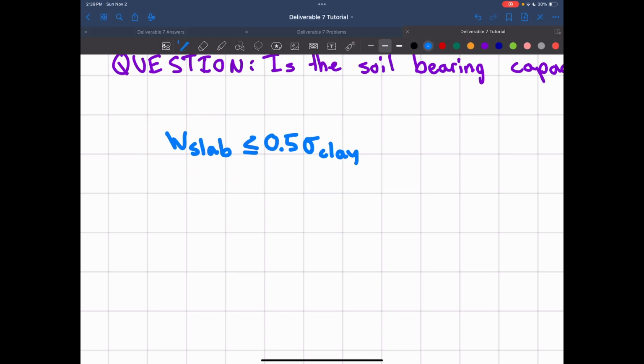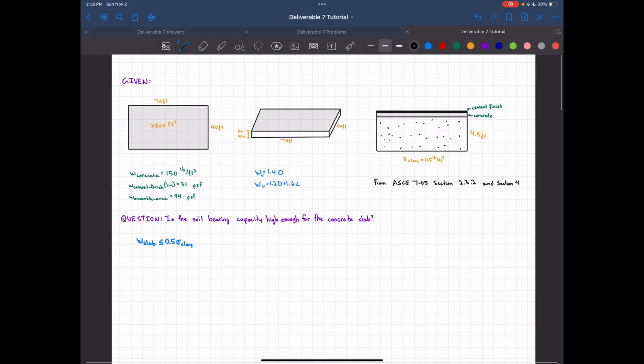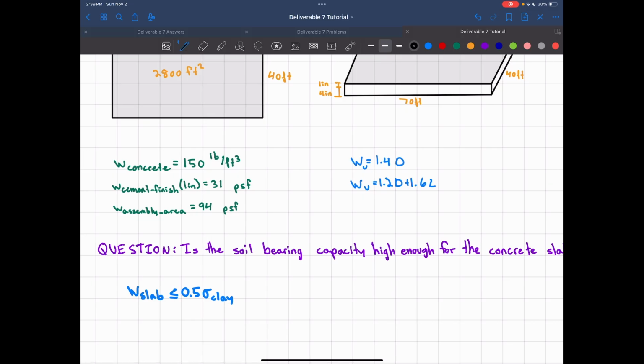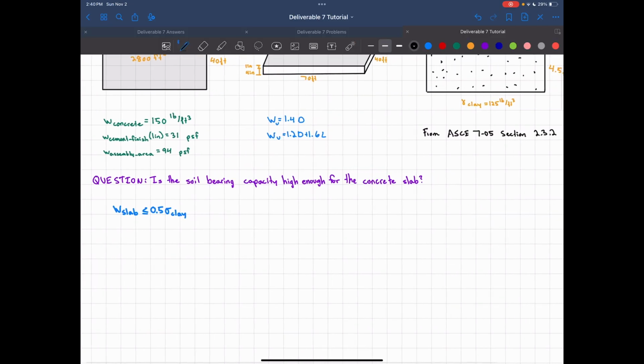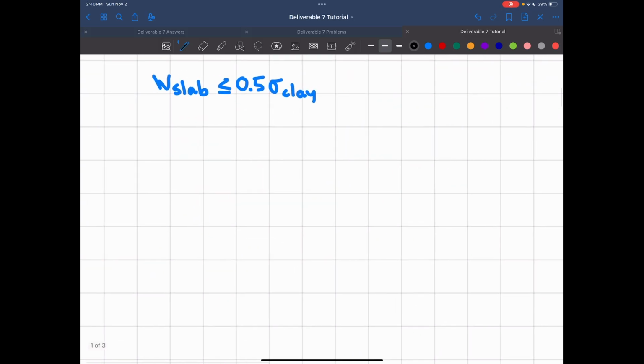This is going back to your structural engineering lecture. We have two dead loads that were given right here, dead load 1 and dead load 2, and then we're given one live load here. We're also given two load combinations that we have to test for. So this is a way of combining different types of loads, and this is another method of implementing a factor of safety. We're taking whatever loads we're expecting and multiplying them by constants and combining them together to get our total load that we're designing for. So let's start by finding all of our dead loads.